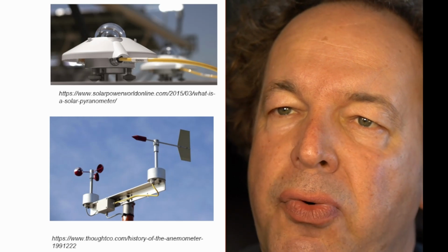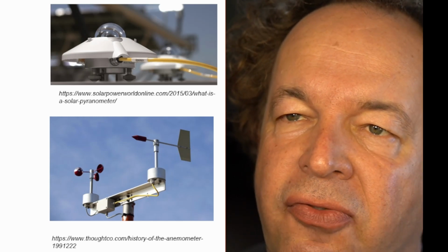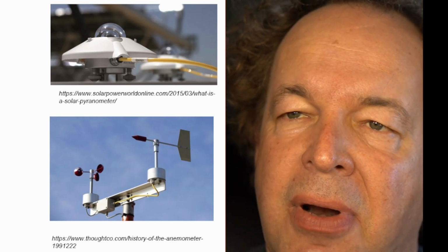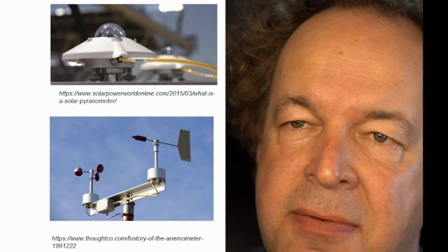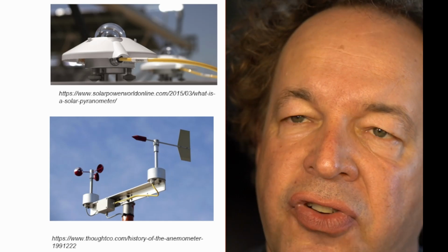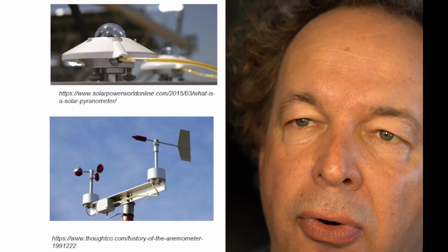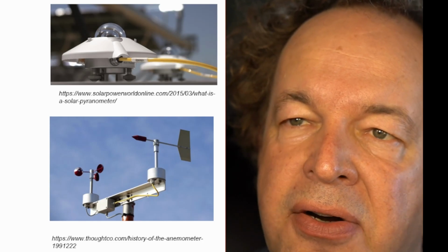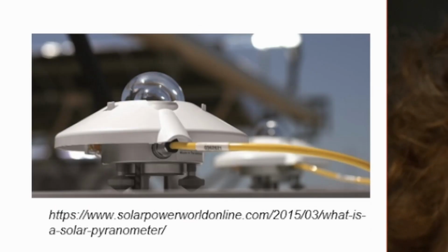The problem is it's not perfectly suitable for the designing of photovoltaic systems, because usually we apply the photovoltaic system on an inclined surface of 30 degrees in Europe, or if you go further north, even steeper. Only if you are close to the equator, horizontal mounting is a preferred option.